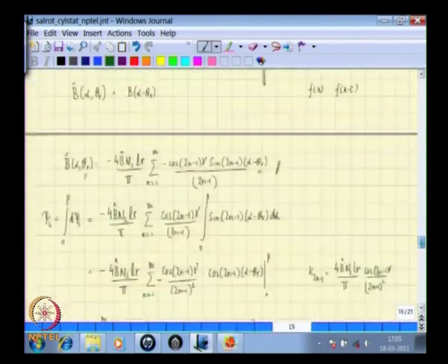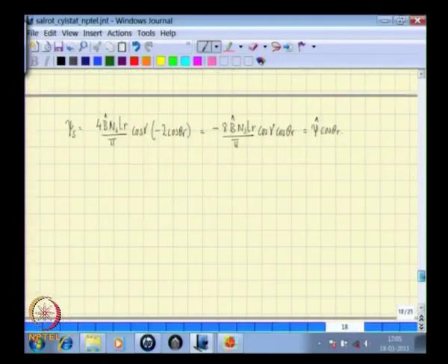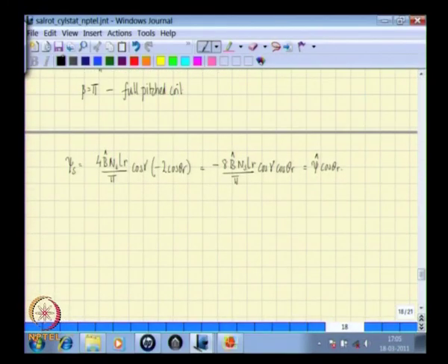Therefore what we can say is, if you apply Ampere's law around that loop of flux, then what we have is H at the air gap multiplied by the air gap length. This is along one air gap of one pole face, and then you have similarly another pole face air gap.